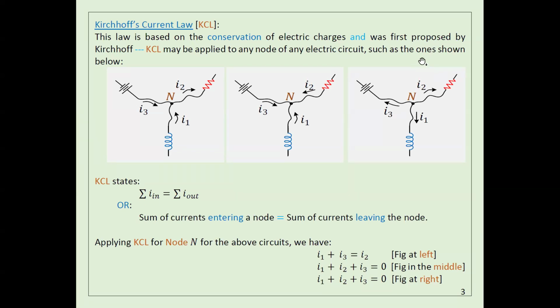It may happen that you see something like that, but I'm sure after you do the calculation, there should be some current input. So the input should equal the output, because this node is not going to generate charges. The charges are coming from the sources and then they are distributed. If you assume the direction this way, it's okay, but after you do the calculation, it should make more sense. Here, because there is no input on this one, out should equal input, which is 0.